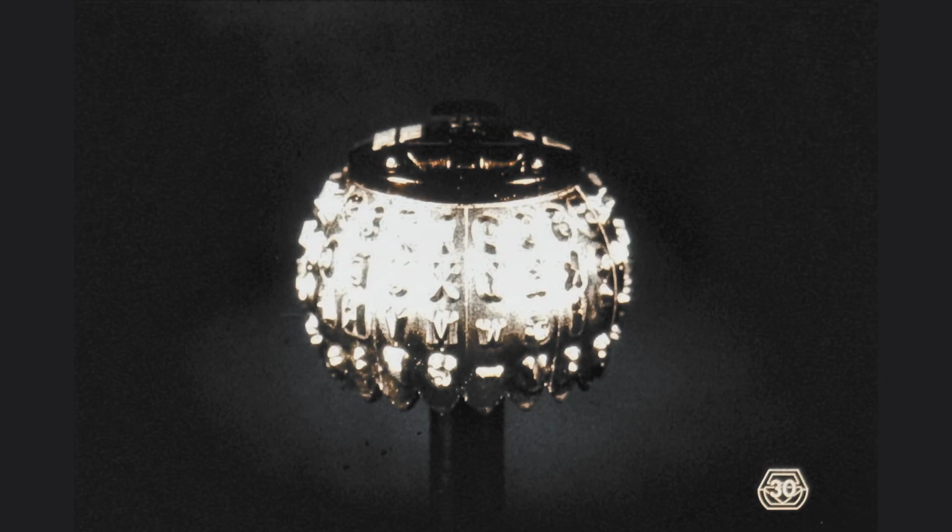The rotation of 180 degrees needed to select between the two hemispheres is the part of the rotate mechanism that IBM calls the shift mechanism. With the shift mechanism, we cut the total number of characters from which we must choose down to 44. You will also notice that in the vertical direction there are 4 rows or belts of characters. With the tilt mechanism, we can choose any one of these 4, cutting the number of characters to choose from down to 11. Of these 11 characters, one does not require any rotation because it is already in the correct position to print. When the tilt is 0, this character is a Z.